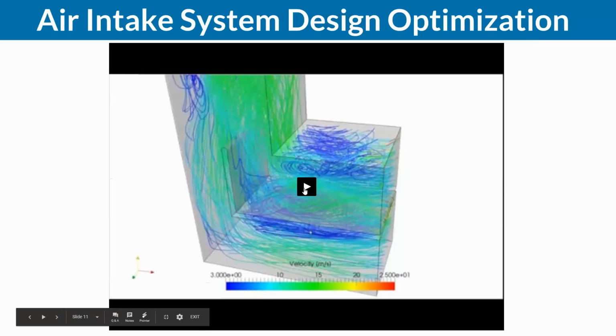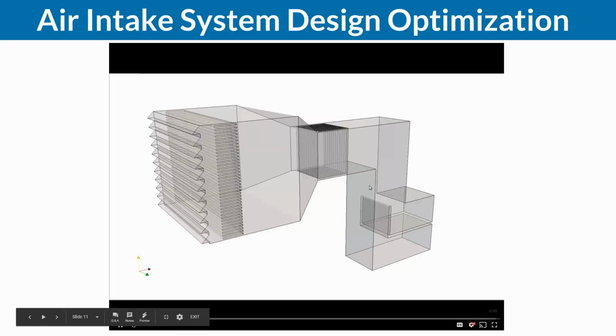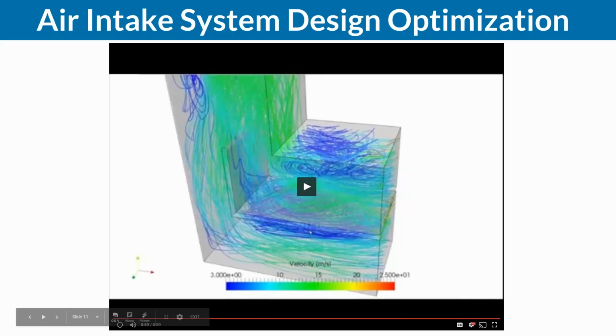Once your simulation ran through, you can post-process the simulation results. So that means you can visualize the fields that you simulated. In that case, it's an incompressible flow simulation. So we can afterwards visualize pressure, velocities, and turbulent quantities. In that case, we're mostly interested in velocity and pressure, right? And so this is, I'm sorry, I skipped that one.